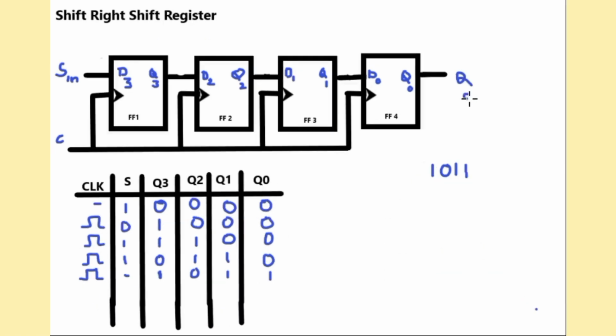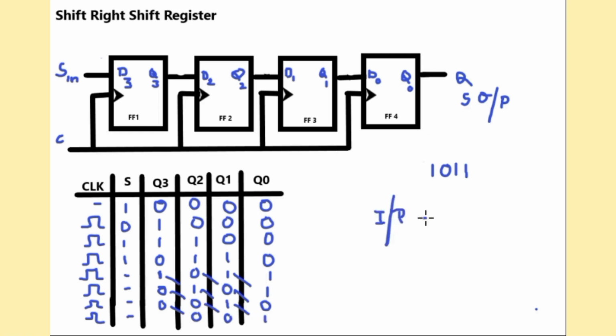As we can see in the register, the output of each flip-flop is connected to the input of the following flip-flop, and if we continue to apply 4 other clock pulses, the serial input data starts coming out of Q0 one by one. This is due to mere shifting of the data available after the 4 clock pulses. The input is serial and the output is also serial, so the operation is called serial input and serial output operation, and the desired data is stored.